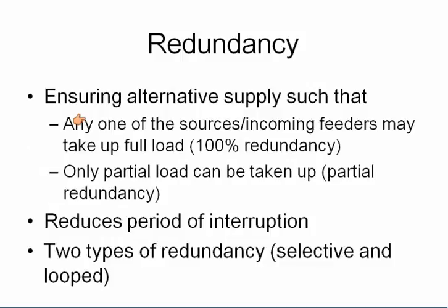Yes. Redundancy. Redundancy means ensuring alternate supply. So you can have a second feeder or you can have a generator for part load. So you can have 100% redundancy with a spare feeder, or you can have a local generator for part load. Reduces interruption time. Types of redundancy, selective and looped.